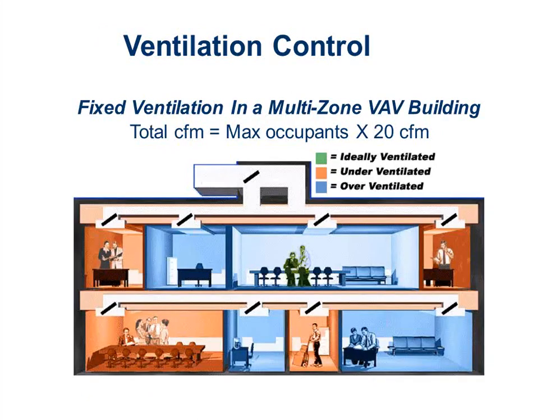If you look at zone-based systems, which we're not going to focus on too much today, but we'll talk about a little bit so everybody knows what's going on there. You've got an outside air louver and an air handler as shown up here. Let's see if we can actually, hopefully you guys can all see my mouse on the screen here. So we've got the outside air louver on the outdoor air handler, and this guy's job here is to bring in outside air for all of the zones.